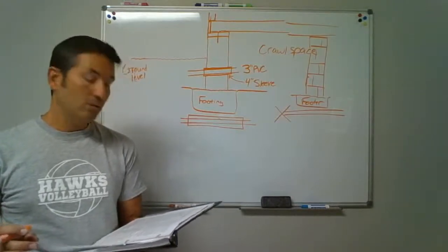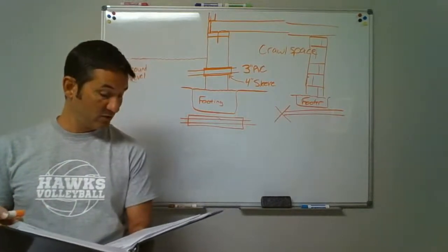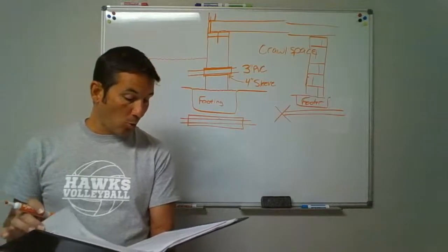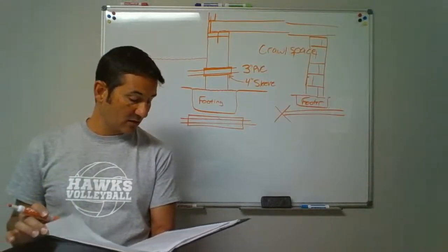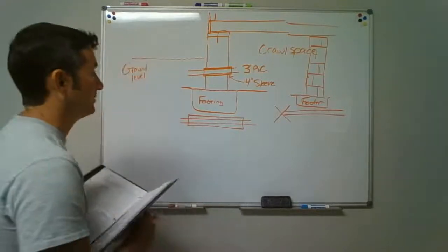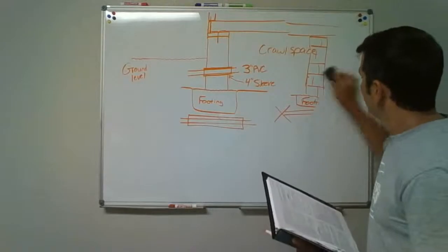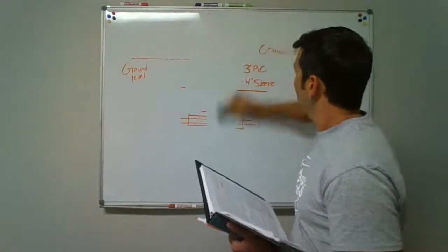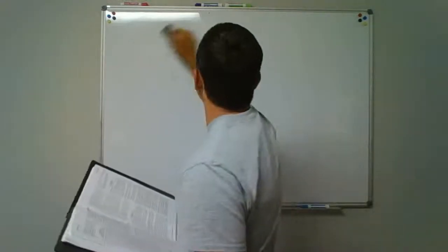305.4. Now, how about protecting them from freezing? We don't want those pipes to freeze. What do we have to do for that? Water pipes installed in a wall that's exposed to the exterior should be located on the heated side of the wall. Insulation. Okay, you can pause and write down or draw out any of that if you want to, if you need. Get rid of that out of there and move on to the next thing.